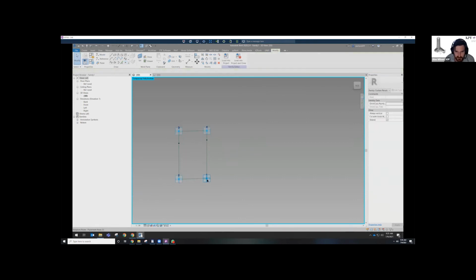Okay. At this point, just make sure everything's working. Okay, so now we have our points placed. Then we're going to connect them with a reference line. Okay, so select the reference line. Make sure you have 3D snapping turned on. If you don't, it's going to base it off a work plane. Okay, so I'm going to turn on 3D snapping. Now you can see as I hover over the point itself, I get that circle showing that it's snapped to that point.